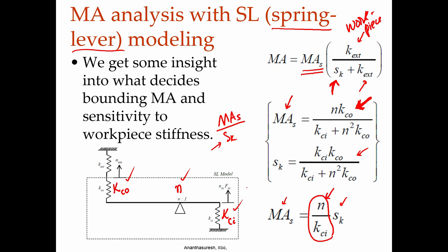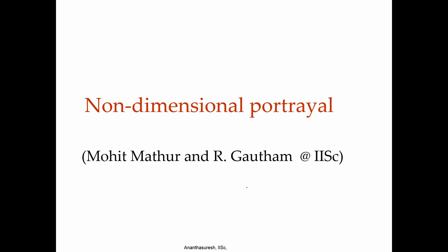These are things that are not accounted for when you do the synthesis the way we have discussed, because those synthesis techniques mostly focus on the functionality, that is the direction in which the input force moves, how input displacement happens, and then how the output force and output displacement do. That is what we have discussed. But now it is a finer point of mechanical advantage, which also can be accounted for with these spring lever model parameters.